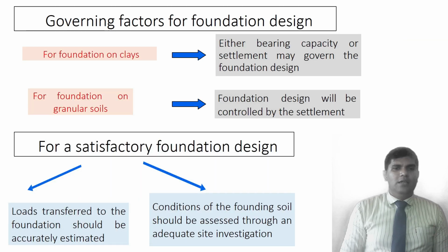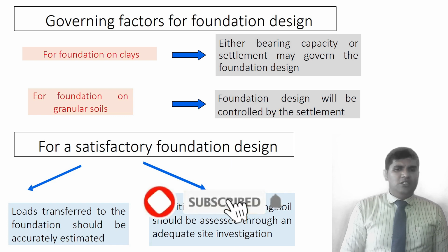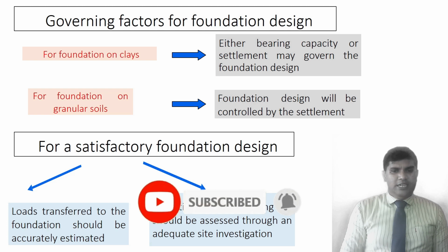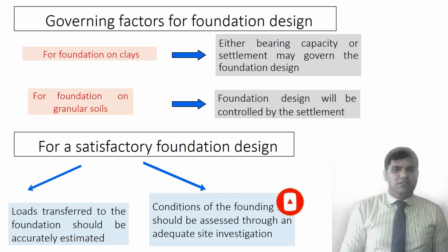Okay, then in the foundation design there are some governing factors. Especially consider constructing the foundation on clay soils, and second, constructing the foundation on granular soil. What are the governing factors? Especially in clay, bearing capacity or settlement may govern the foundation design, and in granular soil we have to control the settlement. So foundation designs will be controlled by the settlement.